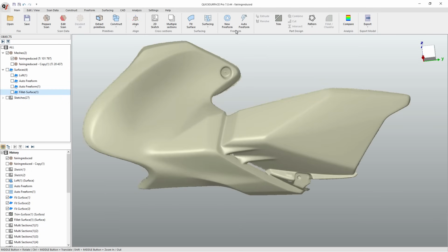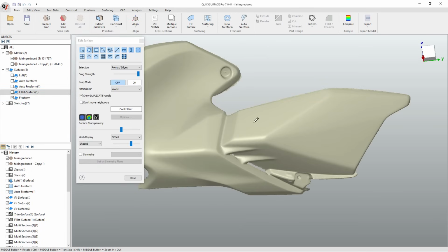There is one last thing I didn't mention that you can do in both the light version and pro version of QuickSurface, and this is essentially how we created our surface in Fusion. So what we can do is we can just essentially manually create the freeform bodies by dragging them out. And this does a pretty good job because it also has the analysis tools.